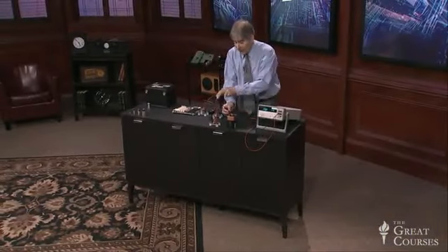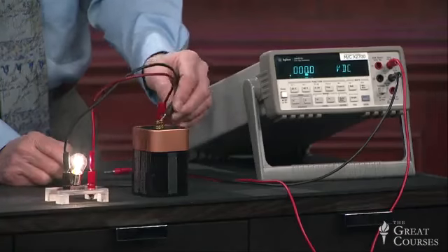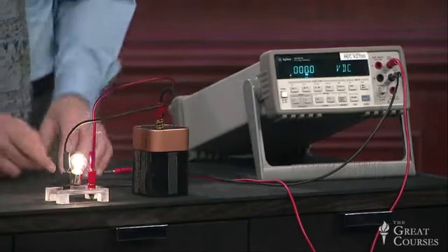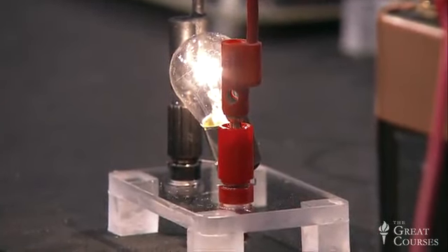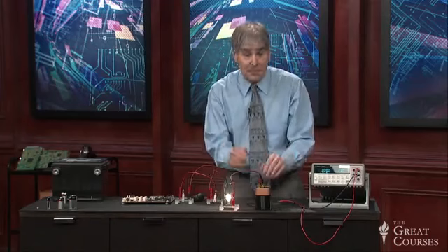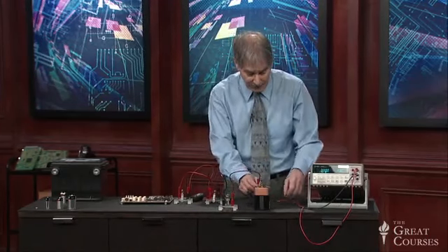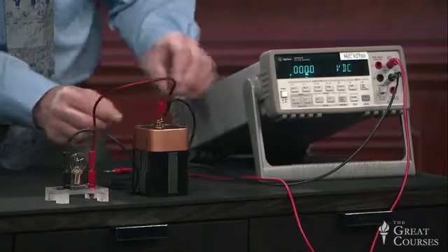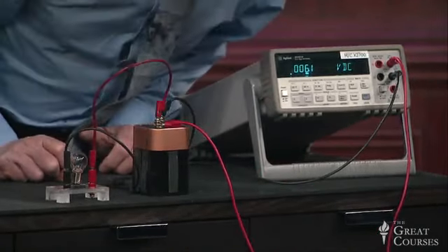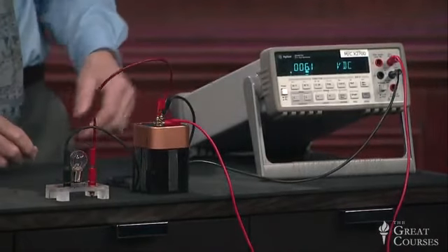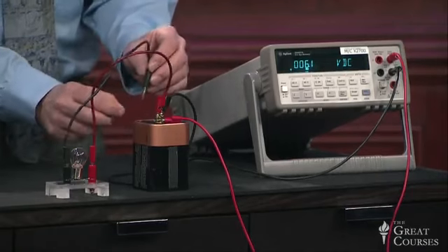Okay, so here I have a simpler circuit, just one light bulb, one resistance connected across a 6-volt battery. It's a beefier light bulb, which means it takes more current and draws more power from the battery. And there we go. The light bulb is lit. The battery seems to be doing its job well. Now I'm going to disconnect the light bulb, and I'm going to connect the voltmeter so I can read the battery voltage. And there it is, 6.1 volts. That's a reasonably healthy 6-volt battery. It might actually ought to be about 6.3 volts, but that's okay.